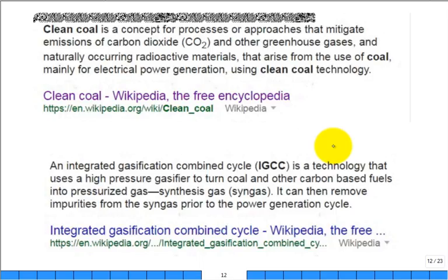Clean coal, for a while that was a buzzword. You can burn and have clean coal. The problem with coal is it's just a lot of carbon. And so you break carbon bonds, so you're going to make CO2. If you take a look at it, methane is cleaner burning because of the 4 H's. And so you're breaking the H and the C bonds. And that liberates a lot of energy with less production of CO2 per BTU or per kilojoule of heat release. But anyway, a lot of work for mechanical engineers in having clean coal-fired power plants.